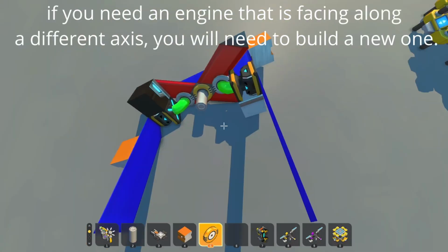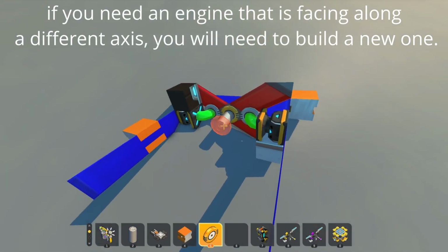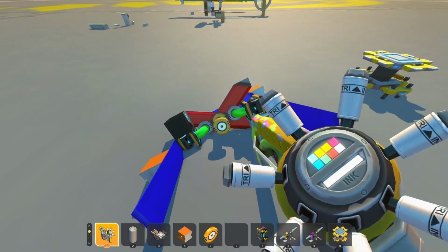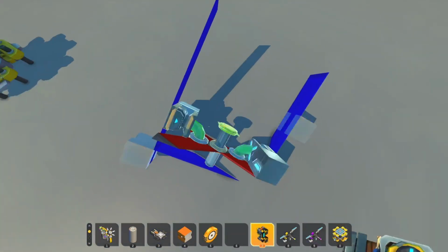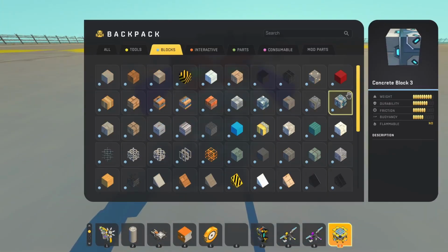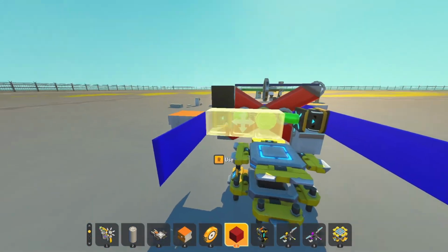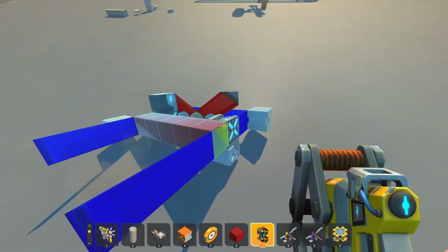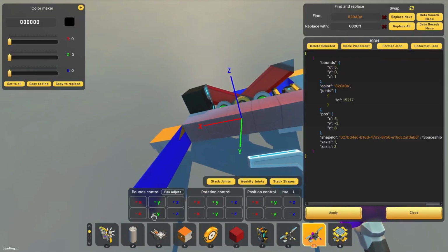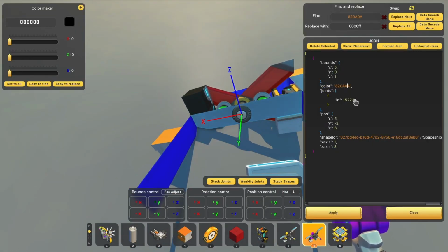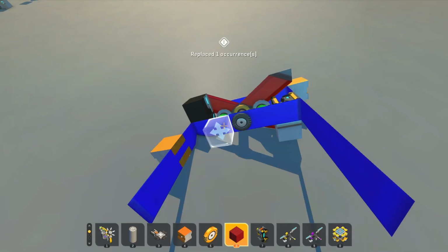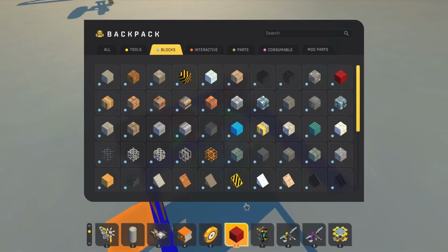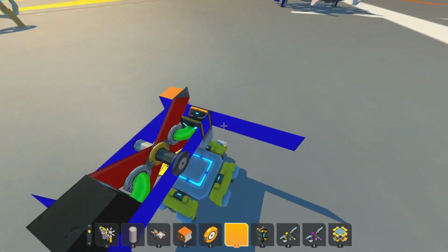Okay, so I colored it so you can see where the different bodies are. So I'm going to place a bearing here, and keep in mind this bearing is placed on this pipe. I'm going to place another block here. I'm going to weld it here, and make it Z-width on this axis, and I'll just paint it to match. Yeah. So we have this, and now this middle Z-width block is sharing a face with these two adjacent ones.